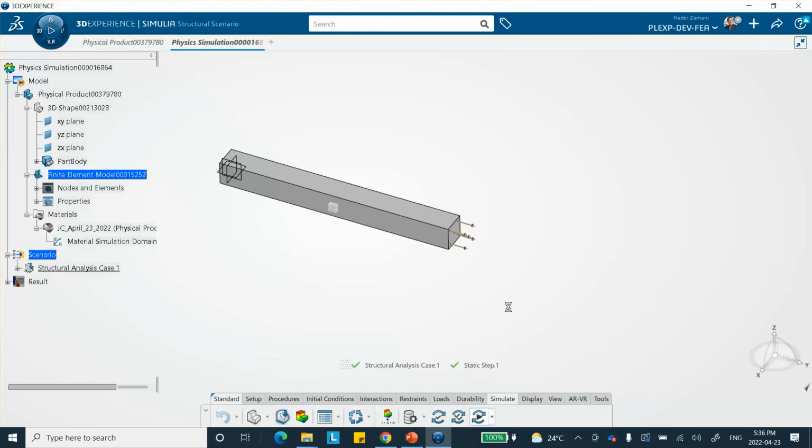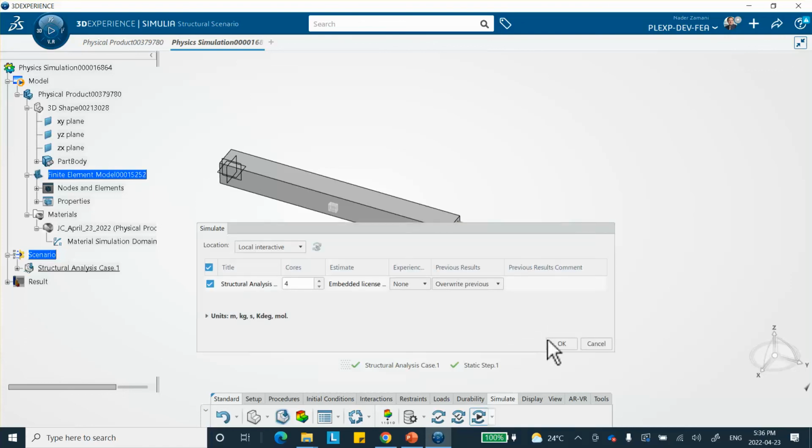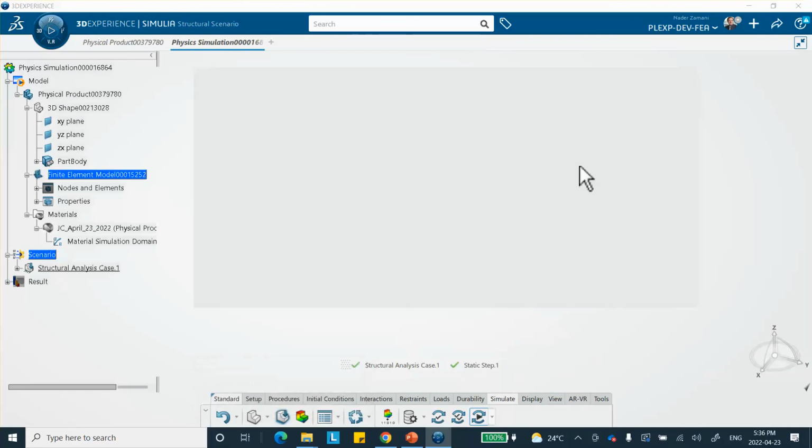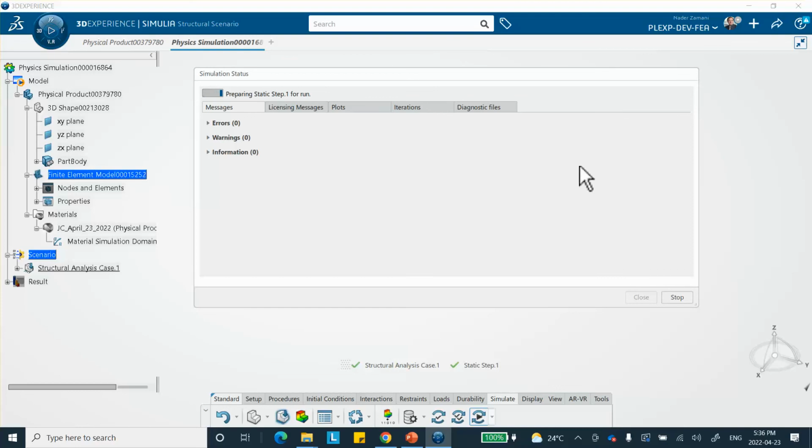Remember, this Johnson-Cook model works for static and dynamic analysis. Therefore, although I'm doing it for the static case here, if you have a dynamic problem, implicit or explicit, you can still use a Johnson-Cook model, or, for example, give experimental stress strain data at different strain rates and different temperatures if needed. In my problem, I'm ignoring the effect of temperature. But I'm sure if you had asked for temperature effect, there would have been another column where the temperatures are listed. All right, it did run.